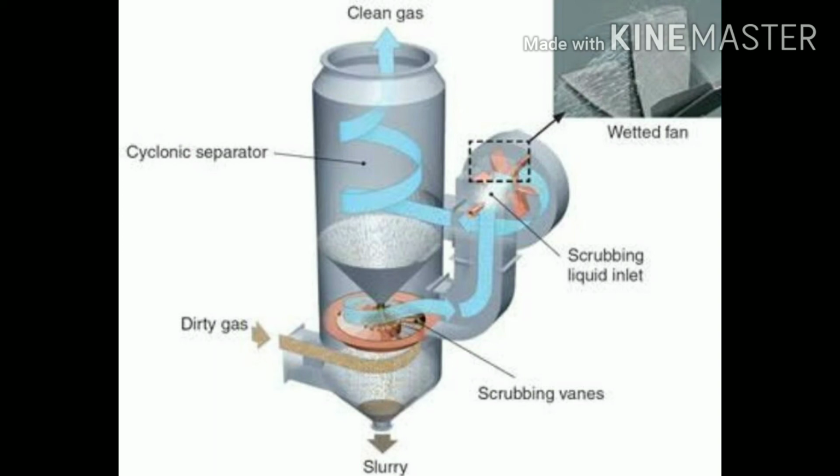It uses lime to neutralize acid gases. Acid gases can be removed by dry scrubber. And the advantage of this method is that it reduces explosion risk. The disadvantage of scrubber is that the particulate matter does not settle easily, and it is difficult to manage the wet sludge.